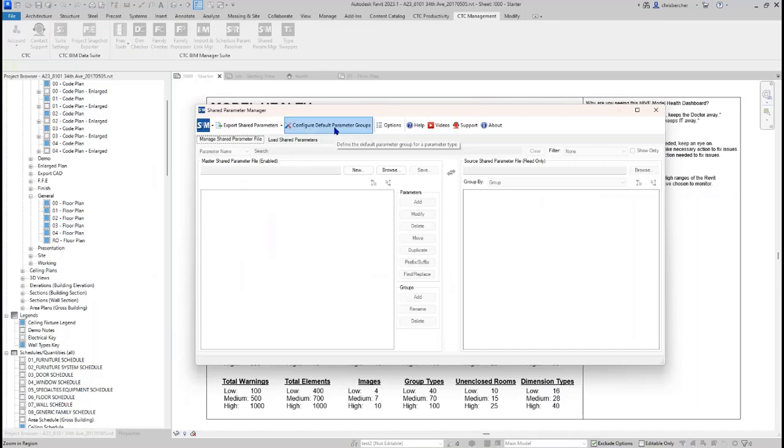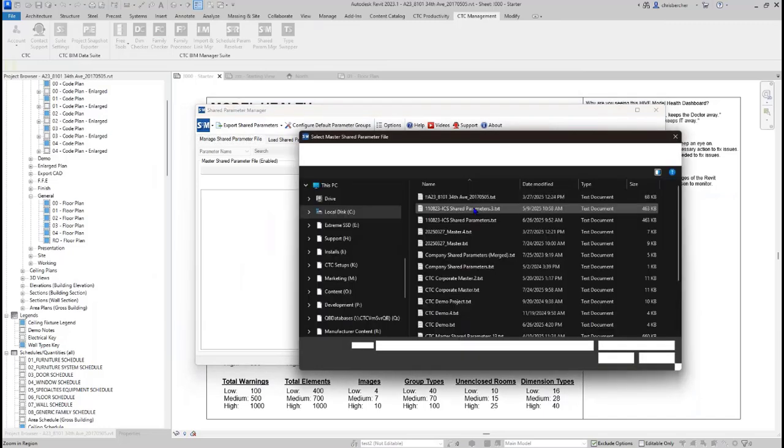So for example, you start a new project and you know at some point you're going to need to add a few project parameters, either for your title block setups or for managing revisions or for managing construction phases, because it's a big enough project and it's going to need that level of coordination, or it's for a particular client, and they have very explicit parameters that they want to use. As long as you have those parameters, you can use them.